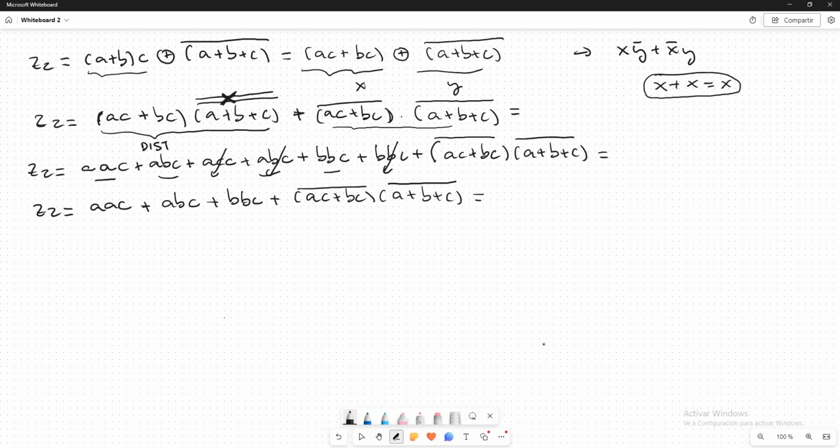And now we know this is the idempotent law, theorem 3. We know as well the dual expression of the idempotent law is this. So if we have a literal that is repeated in a product, we can remove the literal as well.